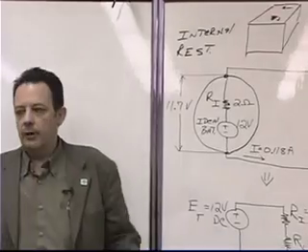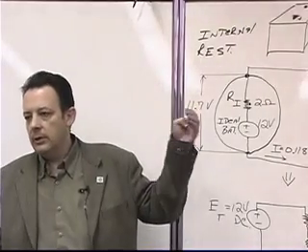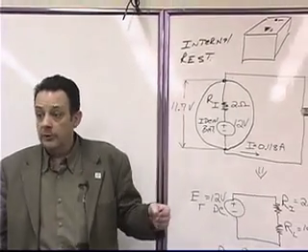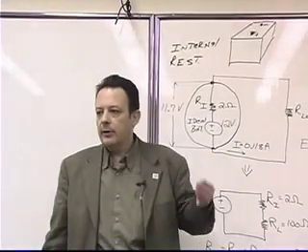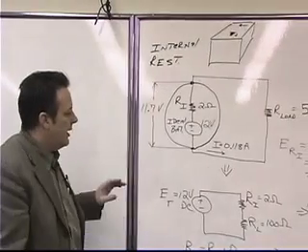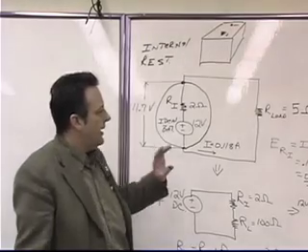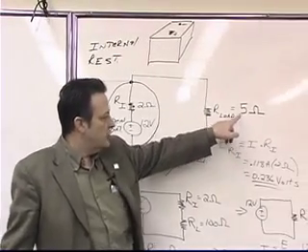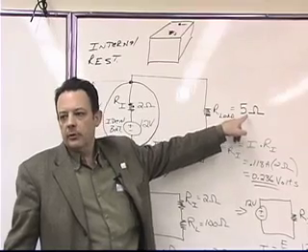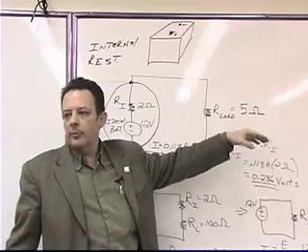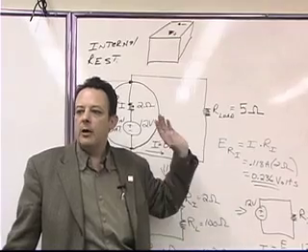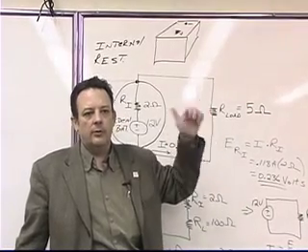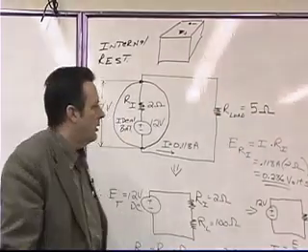Might take 100 hair dryers, I don't know, but at some point we could get to a total load resistance of 5 ohms by adding enough hair dryers, okay? So now let's go back and reanalyze our circuit when our load resistance has changed from 100 ohms to 5 ohms. The number's gone down, which means the amount of load has gone up, or the number of hair dryers connected has gone up.